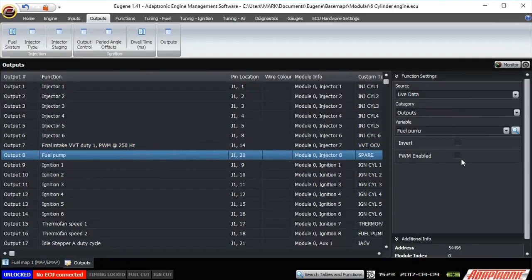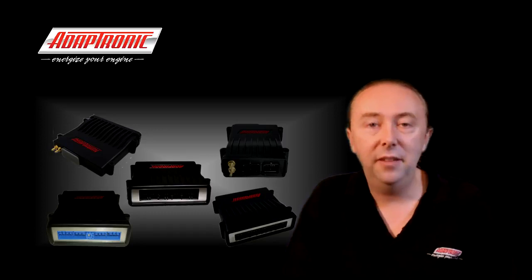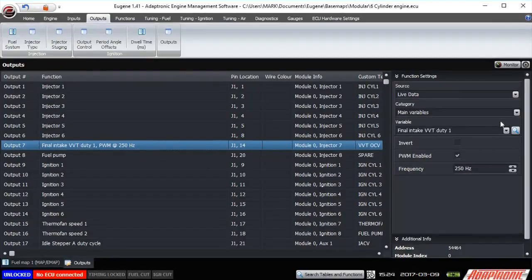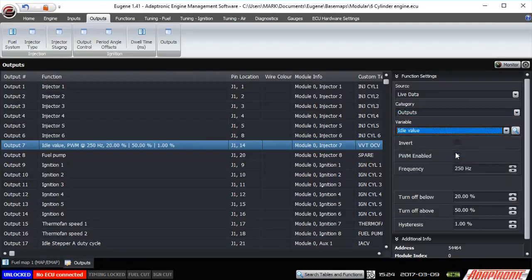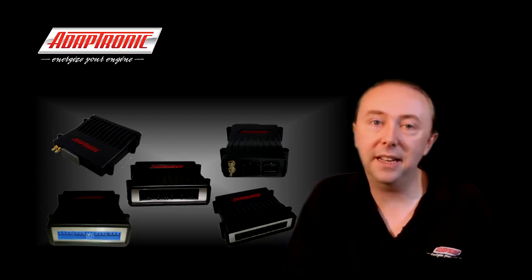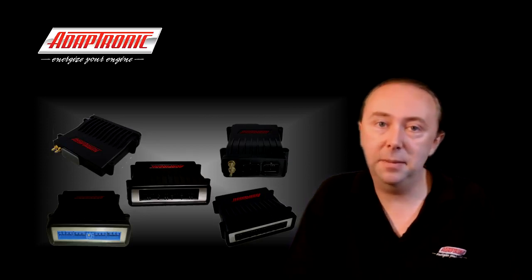For argument's sake, let's assume that we want to use injector output 7 to be an idle valve which pulse width modulates at 250 Hz. What you would do is select that output and then select the type. Do this by selecting outputs as the variable category and then idle effort as the output channel. Then enter the frequency of 250 Hz. The procedure is the same for a boost control output, but normally in that case you'd run a lower frequency, for example 30 Hz. Let's do a more complex example now.